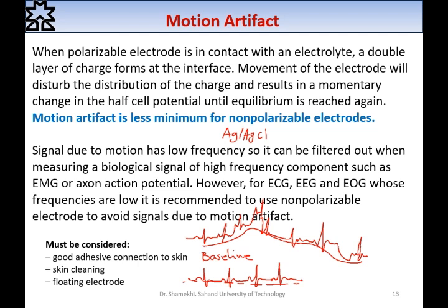To overcome this problem, we should use a good adhesive connection to the skin. We use good adhesive electrodes, and we should fix them. We should clean the skin and use some electrodes. We call them floating electrodes. But the main solution is using a fixed electrode, a good electrode with good adhesive.